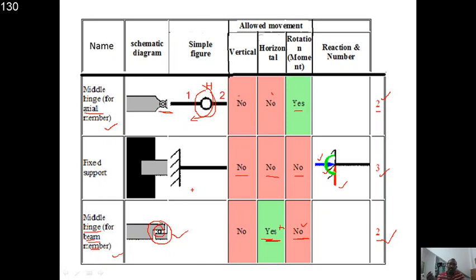But wherever it is earthquake prone, we require some flexibility in the structure. There we require some sort of support different from the fixed support, or partial fixity is required for earthquake structures.